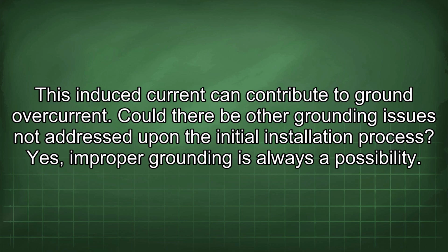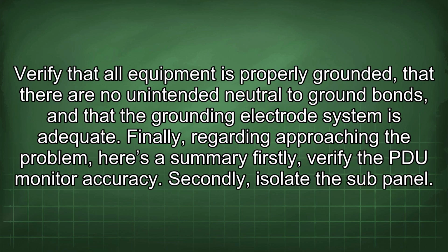Could there be other grounding issues not addressed upon the initial installation process? Yes, improper grounding is always a possibility. Verify that all equipment is properly grounded, that there are no unintended neutral to ground bonds, and that the grounding electrode system is adequate. Finally, regarding approaching the problem, here's a summary.